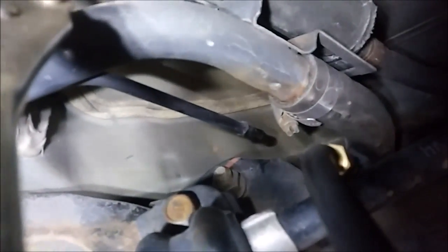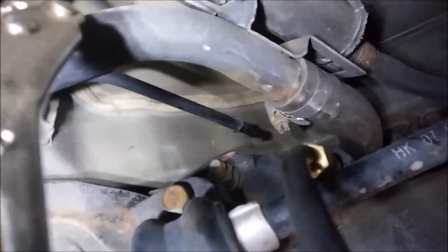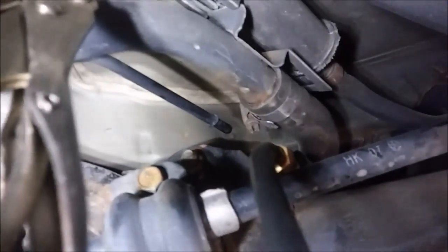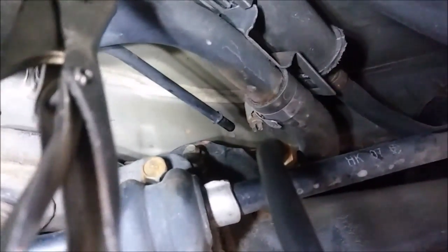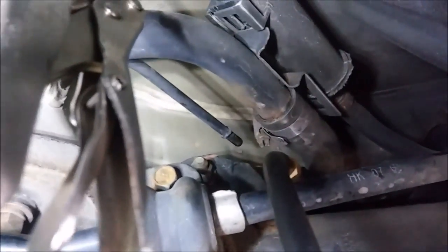One thing to think about, since we disconnected that hose, is that metal pipe right there is now a leak. This system is no longer sealed. That's okay. We're going to pump smoke into this system, and we're going to seal that ourselves. But before we seal it up, I want to use that as a confirmation that we're getting smoke into this system. So we're going to watch that.